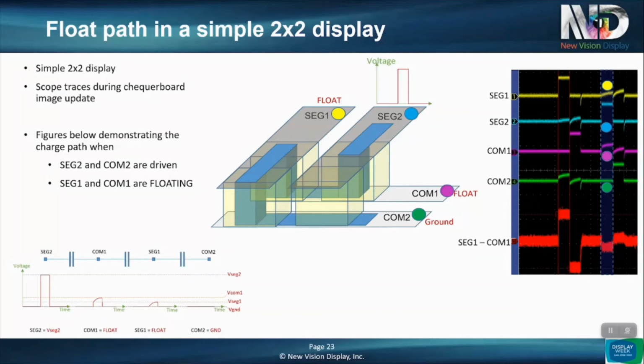They're time dependent because as a liquid crystal reorientates, it's changing its capacitance, so that changes the balance in this system. So really, what this allows us to do is say, well, what is the form of these floating sections when we have pixels in between these two driven sections? Now let's put those float waveforms schematically into an addressing scheme and see how it turns out.